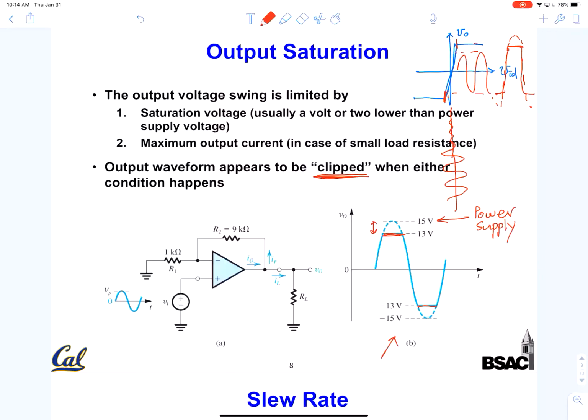Remember, in a linear time-invariant system, we said no new frequency is generated. Whatever you put in, you get out at exactly the same frequency. But with distortion, you introduce new frequencies. This is equivalent to seeing an illusion or ghost image. They are not really there in the input. They are there because of the nonlinear distortions of the amplifier used to pick up the signal. We hope to minimize this, and design it so that this never happens.